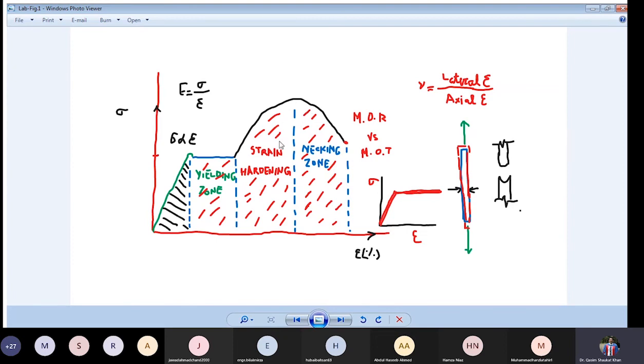Fine. Now in the plastic analysis, instead of taking the bilinear stress strain of the steel, we are considering this strain hardening and the necking zone. We are considering the inelastic range. We are considering the ultimate strength. So this is the basic difference between plastic analysis and the other approaches. In the other approaches, you are just going up to the yielding, but in plastic analysis and design, you are going to the formation of plastic hinges. Means you are going more towards the failure.